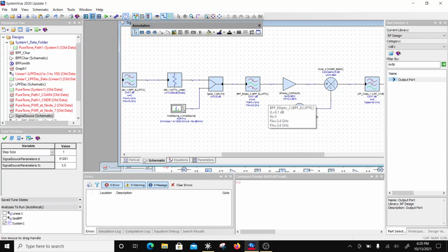One way would be to work with the noise figures to bring the sensitivity numbers down, right? And the other way is to work with the gains. If you go to the Friis formula to calculate cascaded noise figures, you will know what we have to work on.